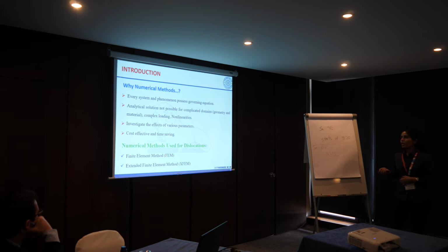Now, why am I opting for extended finite element for doing the simulations of dislocations? As we know, every system has some governing equation. Similar is the case for dislocations. Analytical solutions are not always possible with dislocations, as they have non-linearities and complex loading conditions. So we are considering numerical methods for various parameter considerations. For dislocations, as of now, people are using FEM and XFEM. I am considering the XFEM so that we can model the singularities at the dislocation core.